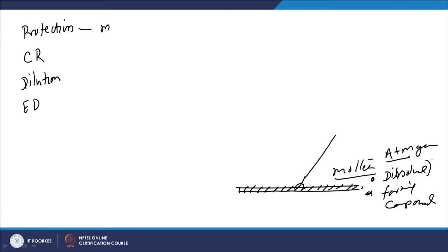Dissolution of the gases and their limited escaping tendency will lead to the formation of pores or blowholes, while the formation of compounds due to interaction of the molten metal with the atmospheric gases will lead to the formation of inclusions. So, it is not good that molten metal is interacting with the atmospheric gases which are present all around, and therefore we need proper protection. For this purpose, different protection approaches are used in different welding processes.